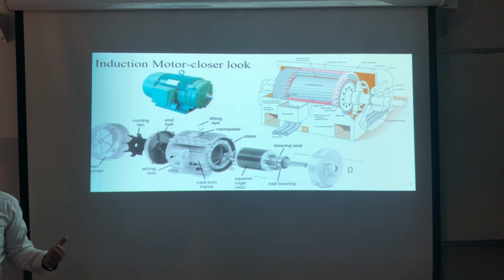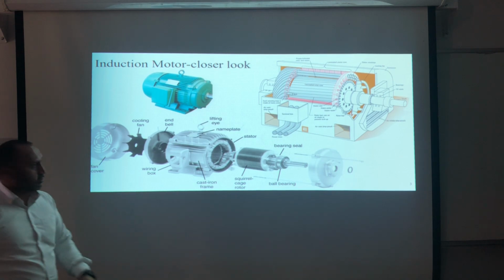In the DC machine, I have slip rings, so this will need maintenance, and that will need maintenance. So I will take advantage of the polyphase induction machine, the three-phase induction machine, which is the workhorse actually, the squirrel cage induction machine. Here I don't have any slip ring, so I don't need to do maintenance. There are no brushes. This is a rigid, compact machine, which means that if I'm comparing two machines of the same rating, I will see that the induction machine has less volume, which means that it will have more torque per volume. Good?